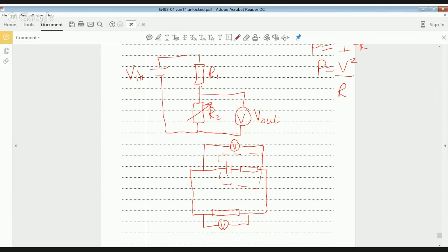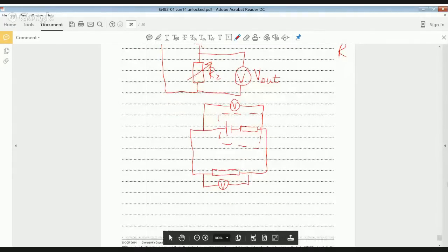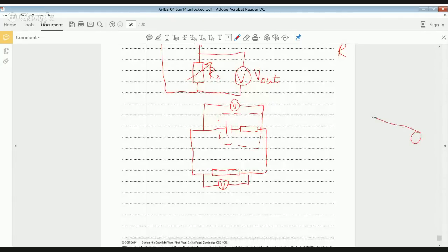How do you know which dimensions to use for the cross-sectional area? That's a really good question. For a normal cable, it should be fairly obvious that this is your cross-sectional area here. So pi r squared. The only thing to be careful of here, they are more likely to give you the diameter of the cable than the radius. So it's going to be pi d squared over 4, or you halve d and feed it in as r.